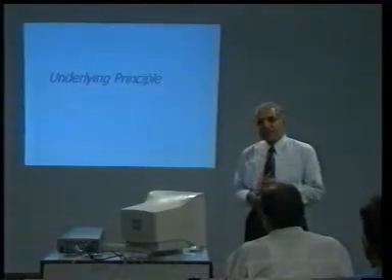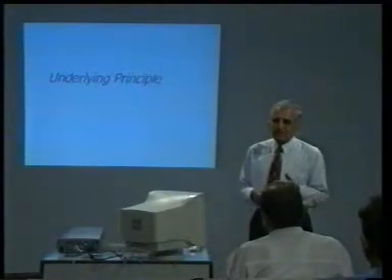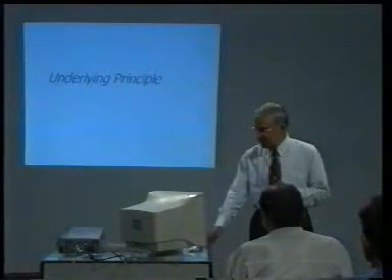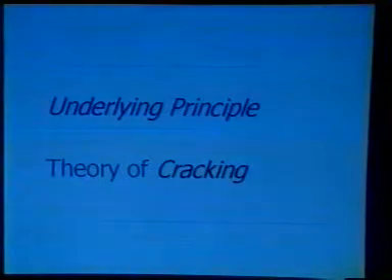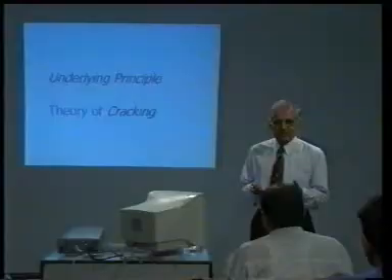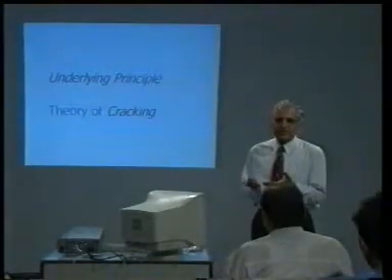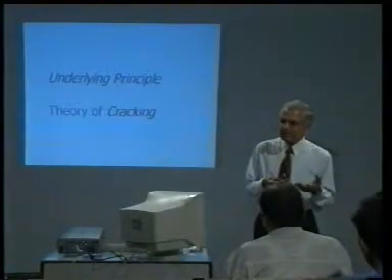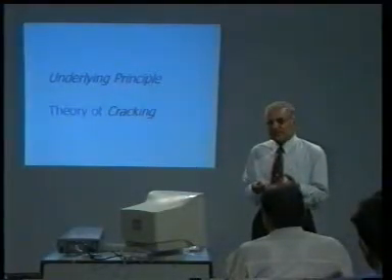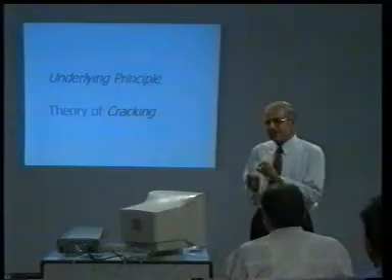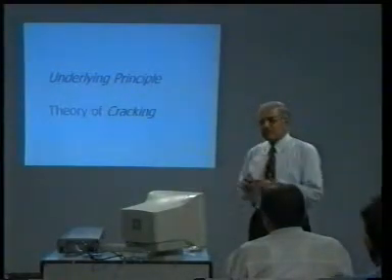Now, the underlying principle of RCC, gentlemen, is the theory of cracking, because unless the concrete cracks in the tension zone, it will not be able to transfer load to the embedded steel. So, you have to understand that process and thereby provide for various conditions that we will be coming to subsequently.